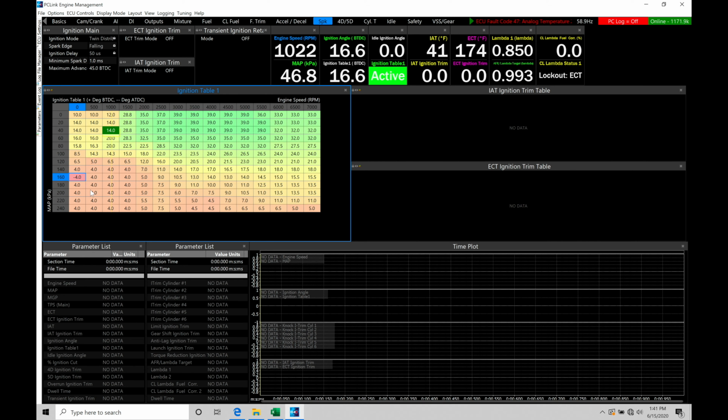So we can see lower values, these are known as late combustion or retarded values. Higher values are known as more advanced values. And we'll find the average value, if we're looking at any spark timing table, is going to be between 15 to 20 degrees. When we're below that, those are retarded values. When we're higher than that, we're more advanced values. So we can see part throttle here has higher advanced values. As we go up in load, we find that the values start to decrease or get more retarded, or later in combustion. And then as we go up in engine RPM, usually we'll find that the values are going to ascend. They're going to get higher as we go up the table.